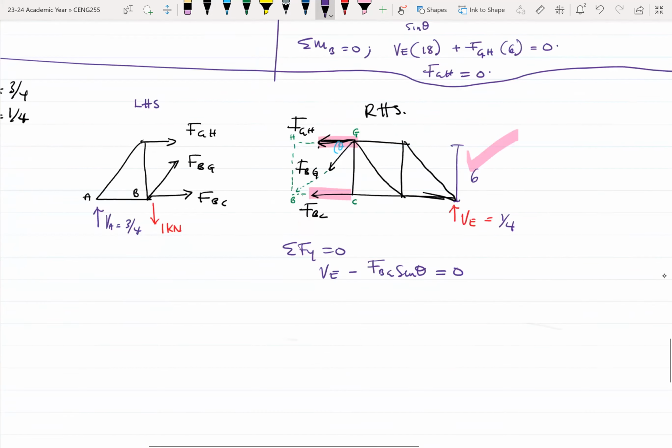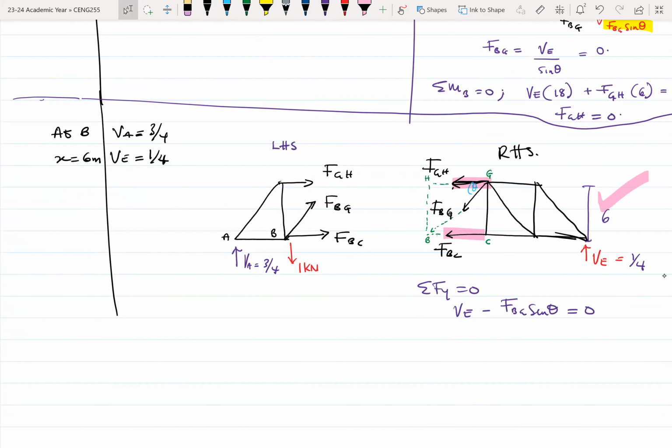Okay, so I just copied everything from 0 to 6 meters. So here at 6 meters, I'd like to slow down, so let me slow down. We have a load acting at B, or the unit load has moved from A to B. Since it has moved from A to B, we are still using the method of sections to determine the forces in the members.